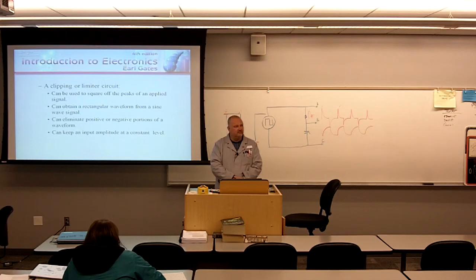So back in the day, Dave Niehaus, who's passed away, of course, this past year, when he was calling a Mariners game, somebody knocks it out of the park and get out the rye bread and salami, and he's yelling into the microphone. If they didn't have a limiter circuit, that transmitter, Cairo or Como or whoever was broadcasting the game, would physically transmit out more power than they were licensed by the FCC. So radio stations have these limiter circuits to keep that amplitude constant so they don't broadcast out more power.